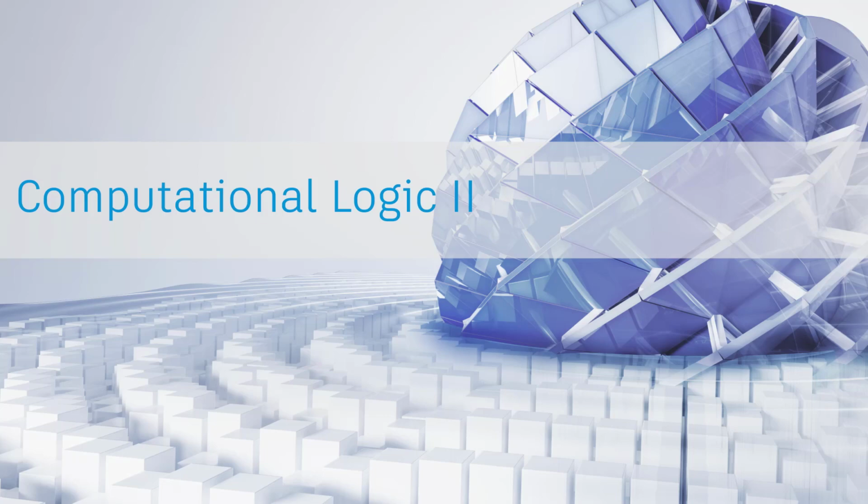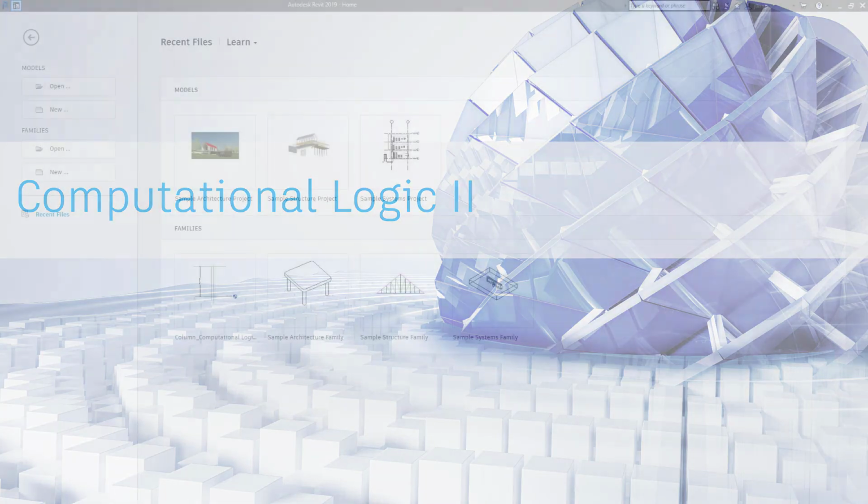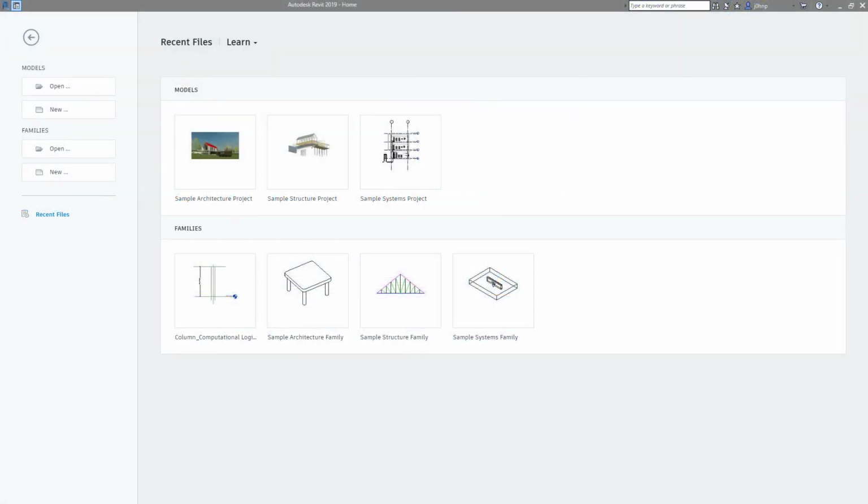In this lesson, we will look at how to instantiate a Revit family element, as well as how to control a family type and instance parameters in Dynamo for Revit. Since we will be automating the placement of Revit families and setting parameters, we need to create a new project file. We could go ahead and click on New and select the default template to continue.